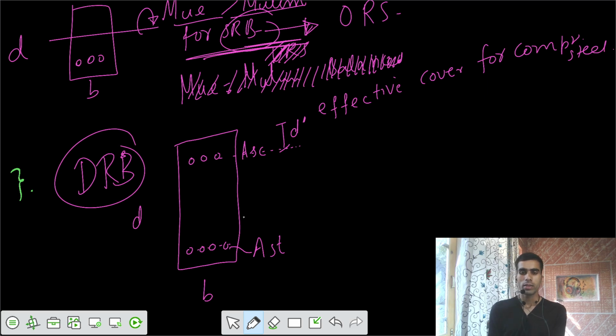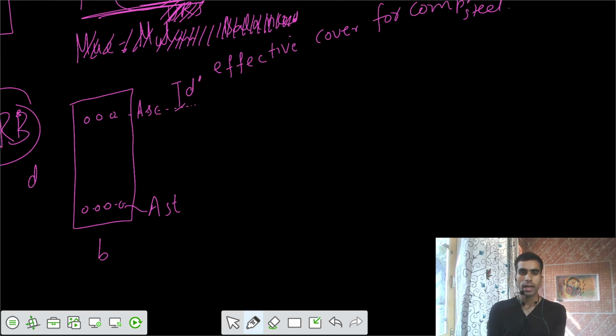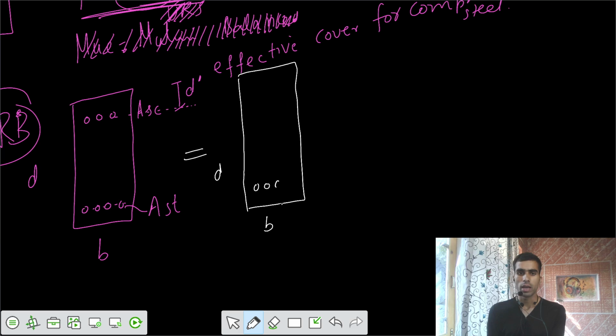Okay. Then we say that the stress block, we are going to treat it in two different beams. We say that there is one beam having the same dimensions B and D, B cross D. Then there is some steel applied here, and this steel we say is equal to the area of steel for limiting condition. For limiting moment of resistance, we said there is some steel placed here. Okay, and then we treat it.